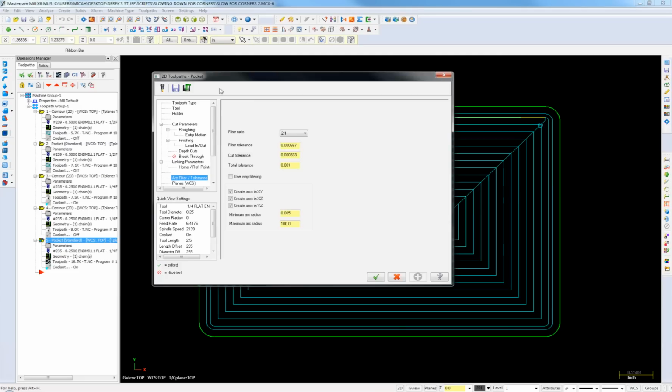Right, because that's one definition that a lot of people don't realize: the arc is going to do along the X and Z. Literally, the arc has to lay along the X and the Z for it to actually do anything. Because if it's off, say 2 or 3 degrees in X along the X axis coming from the Z top, it's not going to change it. It's not going to output a G02 or G03 along with the G18 change.